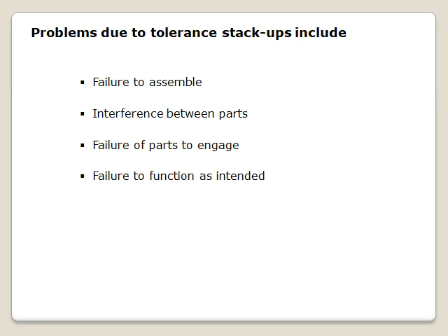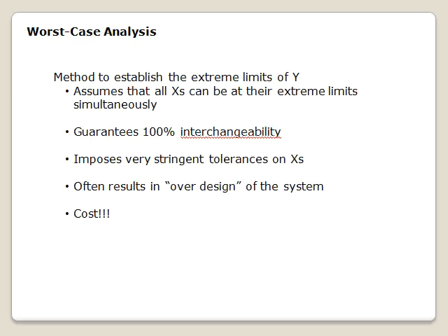Problems due to tolerance stack-up include failure to assemble. If we don't do this, when it is getting assembled, the part may fit, may not fit, if we don't know statistically whether it is a good part or a bad part. Interference between the parts, failure of the parts to engage, failure to function as intended. Here, as a regular practice, most of the time we will follow worst case analysis and the standard deviation method.